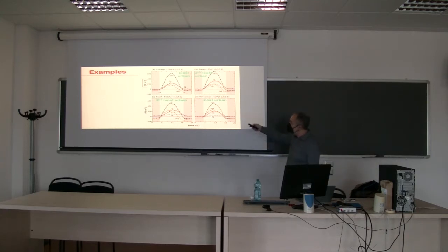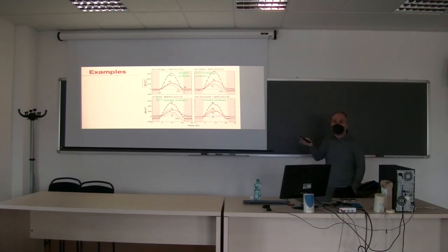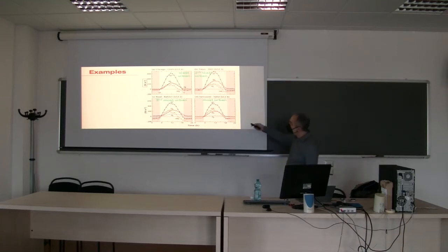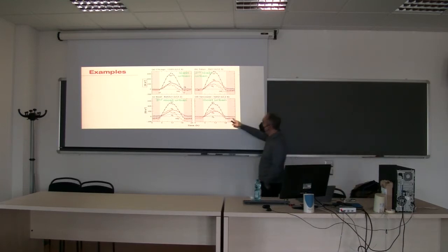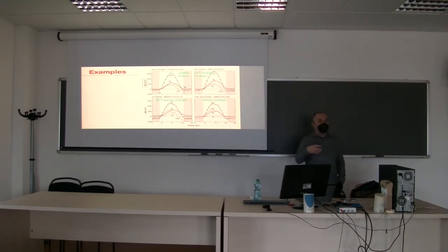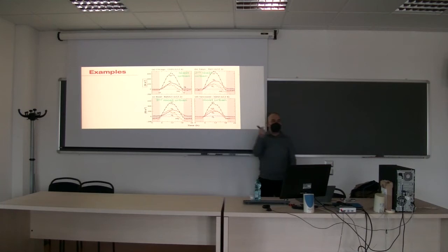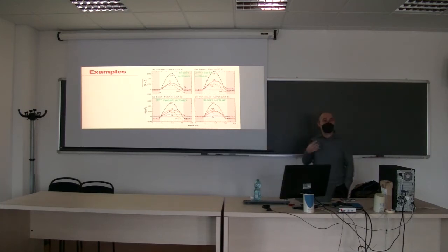But you observe that, for example, if you start at the most rural or most vegetated site, you notice that QH and QE are equal. So the energy going into the atmosphere is half sensible, half latent, because you have a lot of evaporation. And you'll notice that as you go to the most urban, this balance completely changes. So here QH becomes larger than QE, which is the blue. Here the difference goes larger, and here QE is almost negligible, and QH is much, much larger. So as you go to areas with less and less vegetation, there is less evaporation, and more of the sensible heat flux that's going to heat the air, and this contributes to the urban heat island.